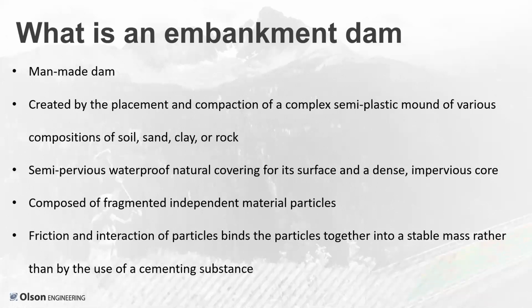There is generally a semi-pervious, waterproof natural covering for the surface. And then generally there is a dense impervious core, typically clay. The materials are fragmented independent material particles, and then friction of the particles binds them together into a stable mass rather than using a cementing substance.